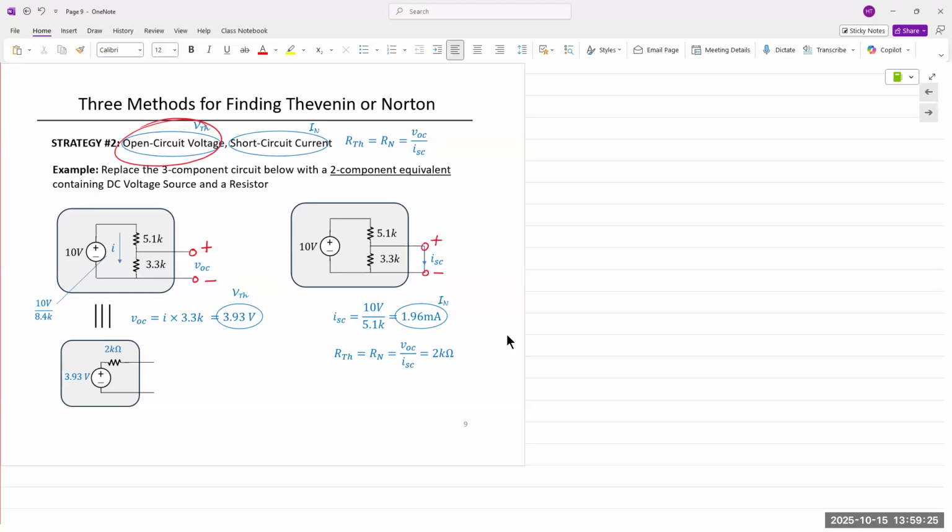So again, you don't have to do anything. Keep that meter connected on those pair of terminals. Switch from voltmeter to current meter or ammeter and measure the current. That's it. Done. So it doesn't take more than a minute to take those two measurements. Well, on the meter, you still have to switch out the terminals physically because voltage and current measurement use different terminals. But the actual measurement, nothing.